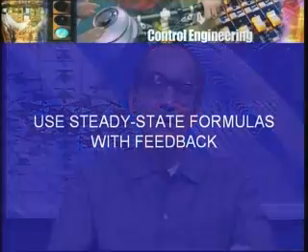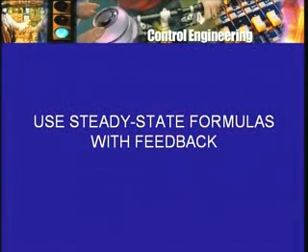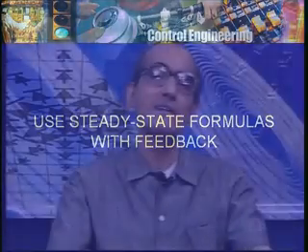Then we cannot avoid steady state error in the presence of disturbances. You can go back and use our formula that we had derived under steady state conditions and play around, substituting different values of load torque or substituting different values for the parameter, let us say KB or KT is changed, and so on. We have done this calculation again, you can do it again, and then do the same thing with feedback. That is, with the feedback arrangement, what will be the error, and see for yourself that the steady state error will be reduced.